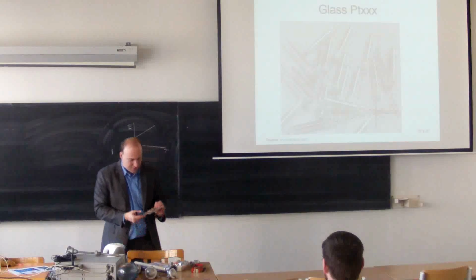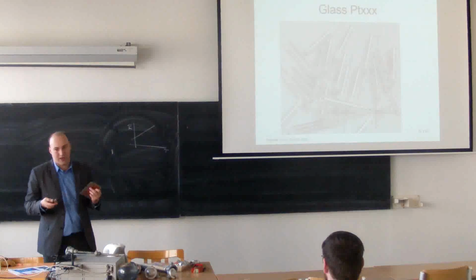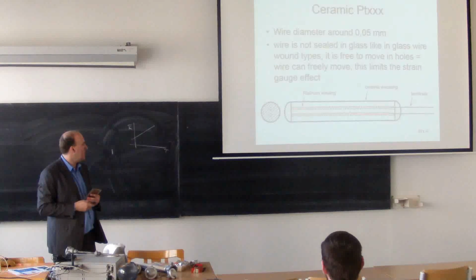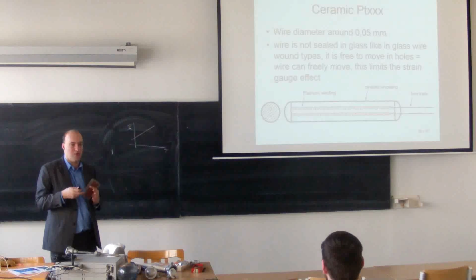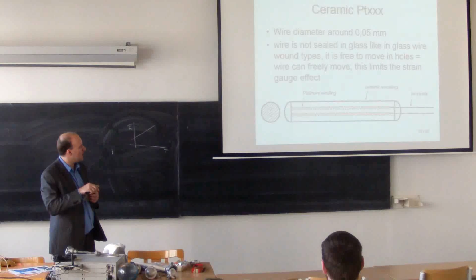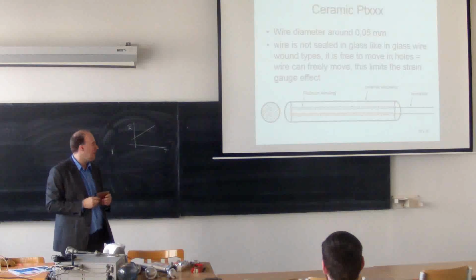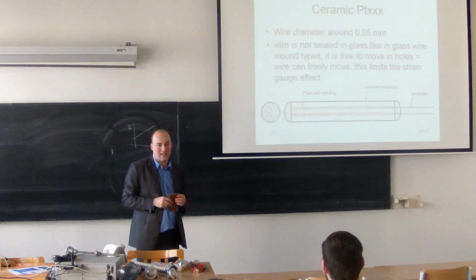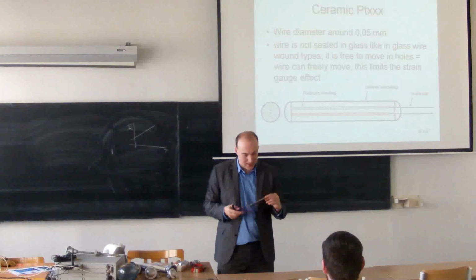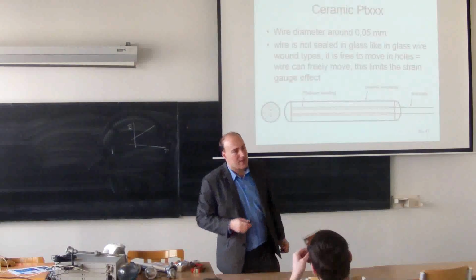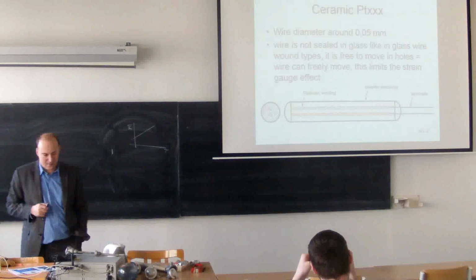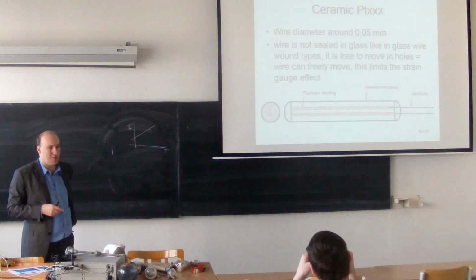For higher temperatures, you need to use the ceramic version of the PT100. And the ceramic version is also a thin platinum wire. Now in ceramic you can see, and ceramics can work for higher temperatures than glass. So this ceramic version can be used up to 850 centigrades. Those are ceramic ones. The price is approximately the same, and it depends on the application.